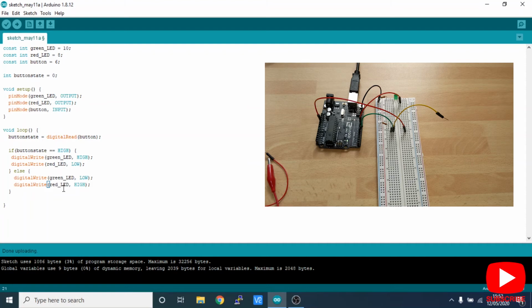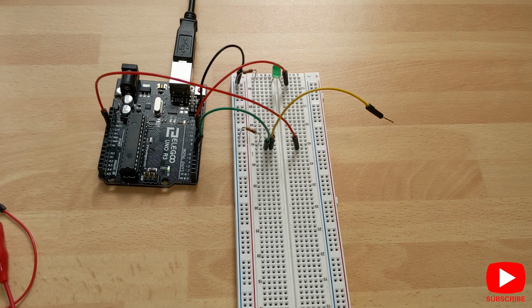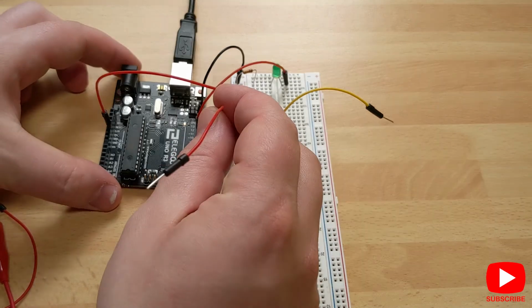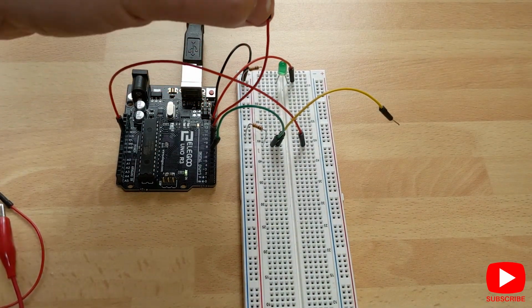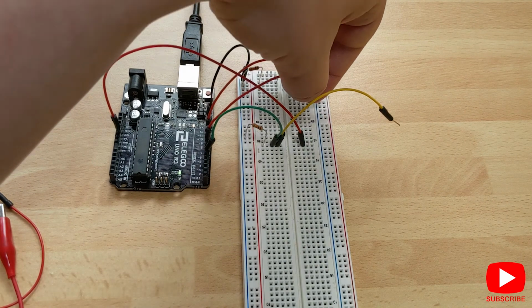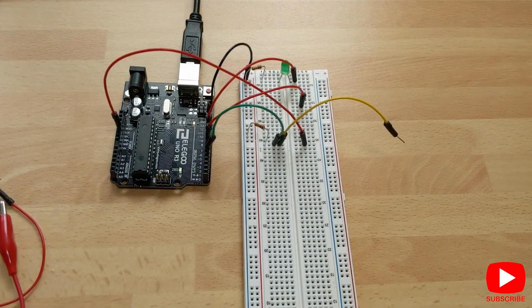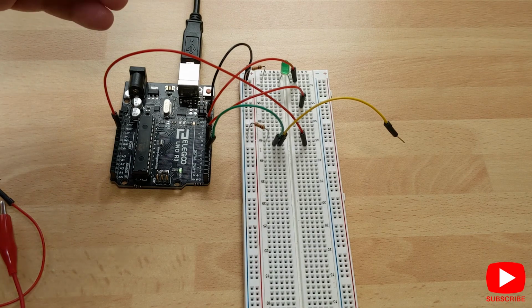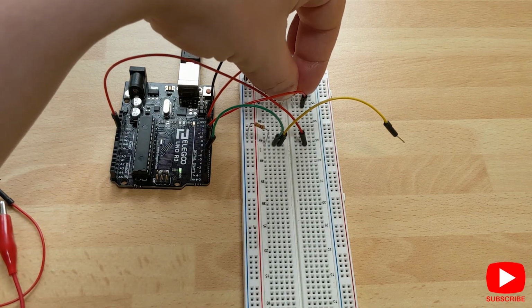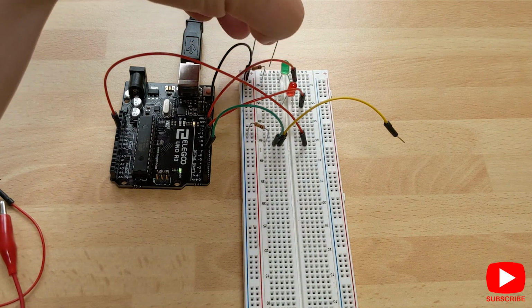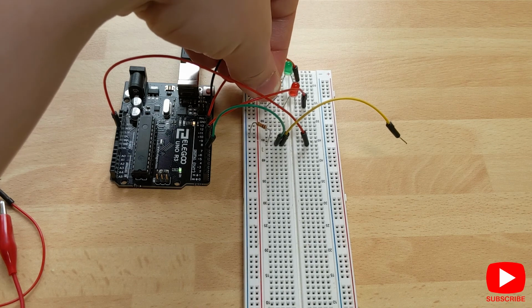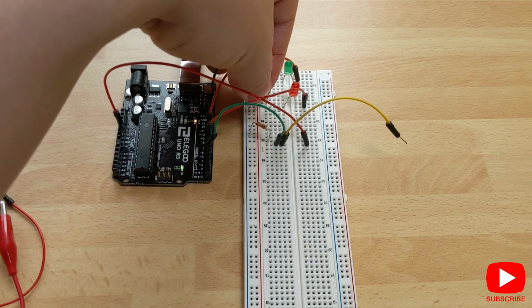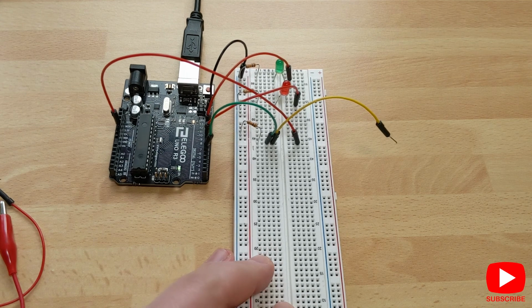Let's jump back over to the hardware here for a second, and we'll have to set up another LED. So we've set that this one is going to be on pin 8. So we'll put our wire here into 8. Oops, bumping the camera. And we'll plug that in up here. And then our LED. And then a resistor to ground. So you can probably tell I've got a limited space here, unfortunately. Okay.